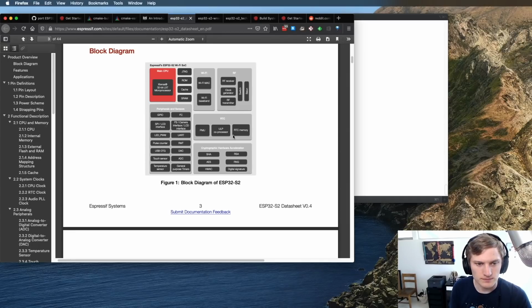So one thing I look for usually in a diagram like this is how things are connected over memory buses. And this is something that's come more on my radar. Some of the other platforms that we're starting to add support for are the STM32F7 and H7, which go as fast as 480 megahertz in the CPU. And then the IMX RT series, the 10XX series, can go up to 600 megahertz.